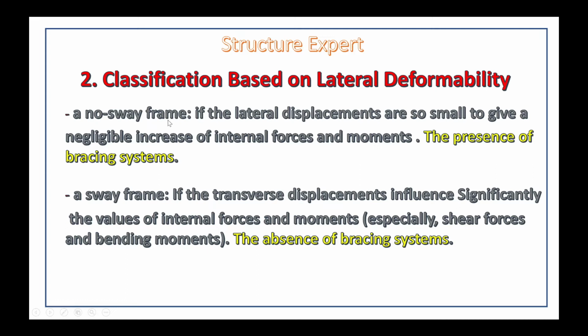A non-sway frame is where the lateral displacements are so small as to give a negligible increase of internal forces or moments, with the presence of the bracing system that can resist at least 80% of horizontal force.